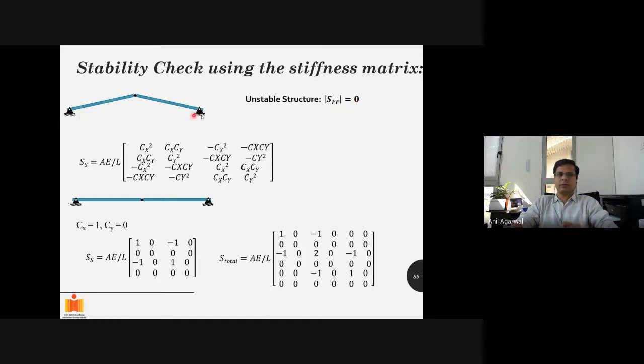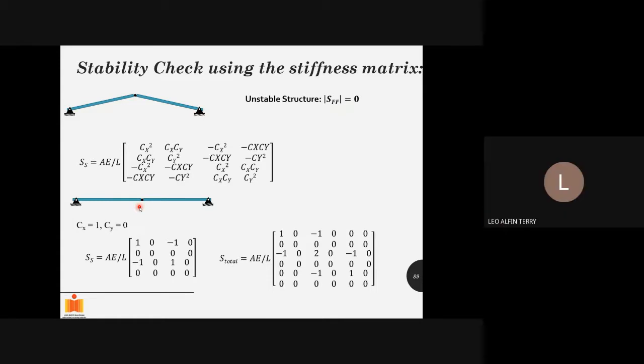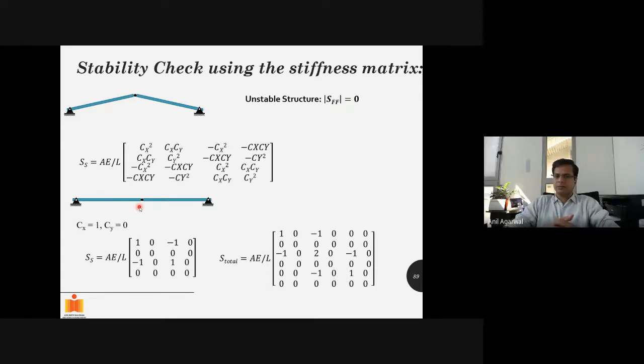So if you visualize this picture, this is kind of a truss, right? It has got 2 supports, both of them are pin supports, they don't move. You have a hinge here, and two truss members. Now imagine that you change this angle slightly, and we can play with this angle. So let's say the member dimensions are such that this member is already almost horizontal. So when it is perfectly horizontal, what kind of a problem is it? Is our system indeterminate? Unstable? Indeterminate?